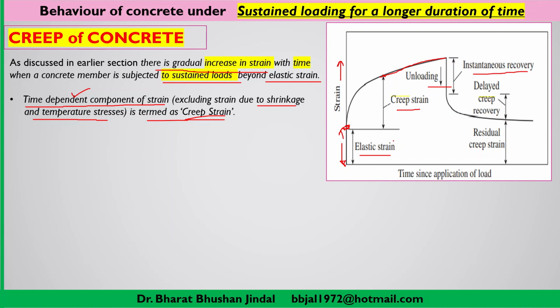So first of all we have gone through the elastic strain, then the creep strain, and after unloading there is instantaneous recovery. After this instantaneous recovery, it will take some time for the creep to recover, to reach its initial stage. So this is known as delayed creep recovery. That means it is not instantaneous recovery, it will take some time.